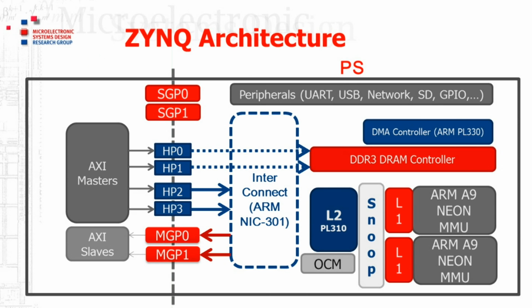The Xilinx ZYNQ also contains another set of AXI slave interfaces for the AXI masters on the programmable logic to drive and to initiate transactions to the address space of the ARM CPU cores.